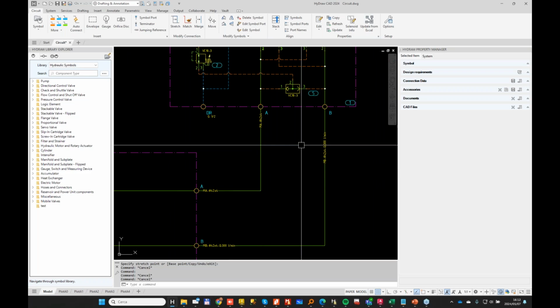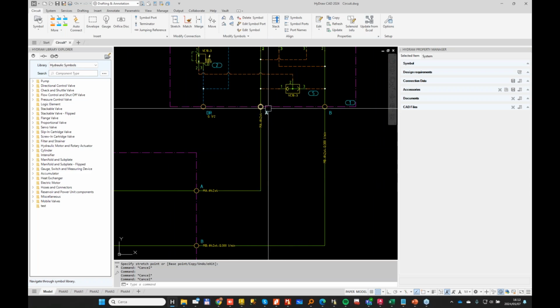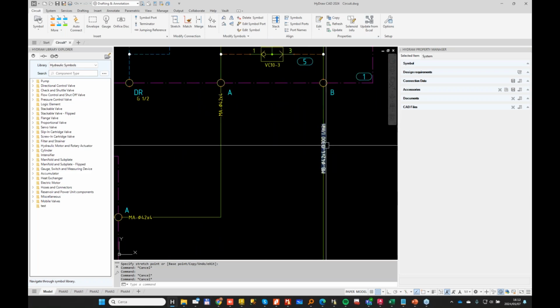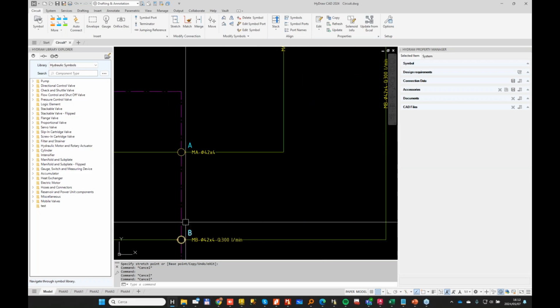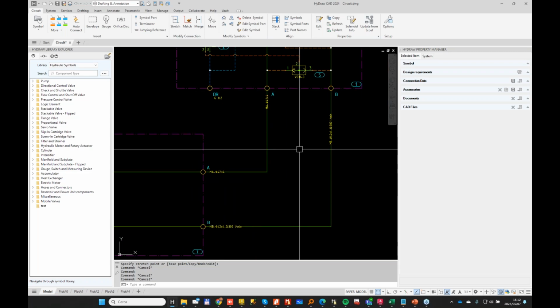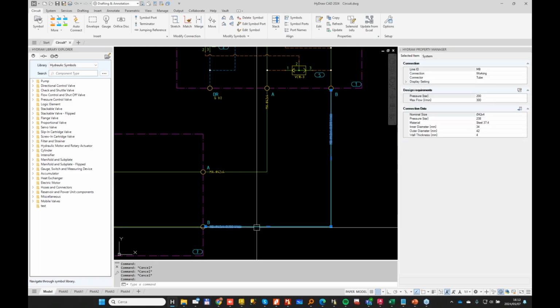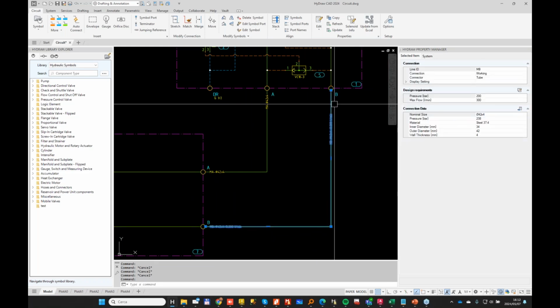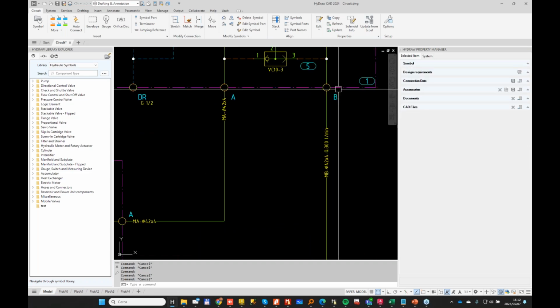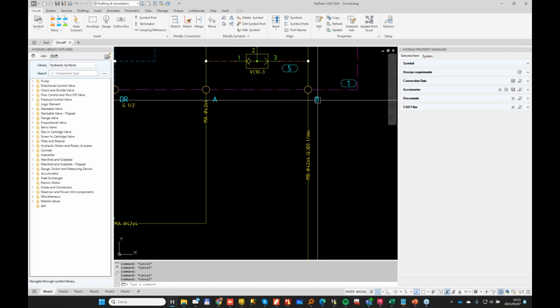So in case your diagram have a very long connection line, this technique may be worth considering, because no matter how you print the diagram, you will see the information on both sides of the connection lines. So with this approach, you can create the custom attributes for connection line and also make them visible by using the library manager. Now let's focus on port size and fittings.